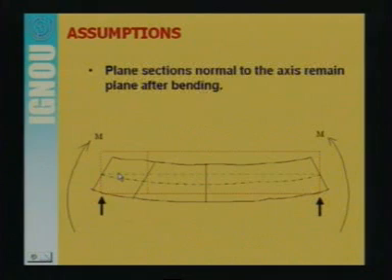Neutral axis is the axis where there is no strain, meaning the strain is 0. Now, under the effect of loading or the bending moments applied to this beam, the beam tries to bend this way, which is shown in black color here. As you can see, the neutral axis also takes a different position from the green one here.